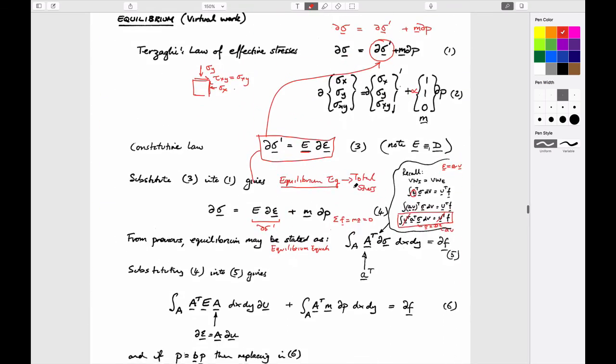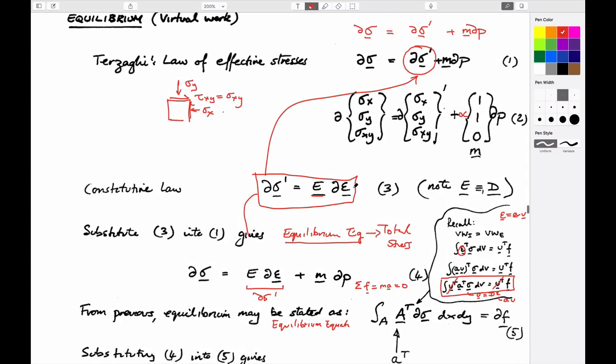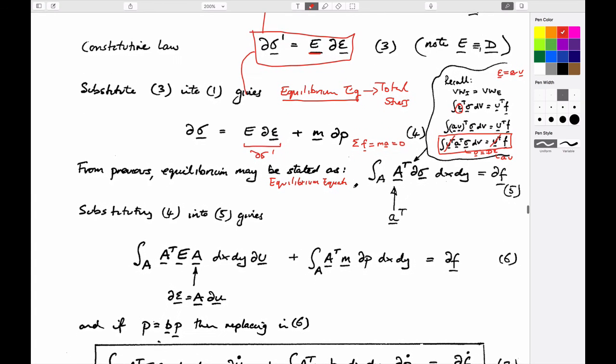It's not important that we understand that, but I think it's maybe a curiosity. And so this is the equilibrium equation. We know what this is. I'm going to write this as uppercase A, just to make the distinction that this is the A matrix for solid mechanics. It's the derivative of the shape functions. It's different from the A matrix for fluid mechanics, right? Because one is 3 by 6 and the other one is 2 by 3. They're different sizes. So we have to make that distinction.